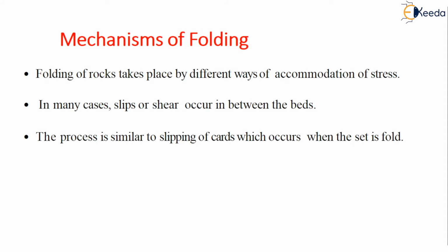Coming to the mechanism of folding, we have to know that folding of rocks takes place in different ways by the accommodation of the stresses. So here in many cases slips or shear occur in between the beds. The process is very much similar to slipping of cards when the set is folded. If they are not allowed to slip over one another, folding of the set cannot take place. Hence, they have to slip over one another.